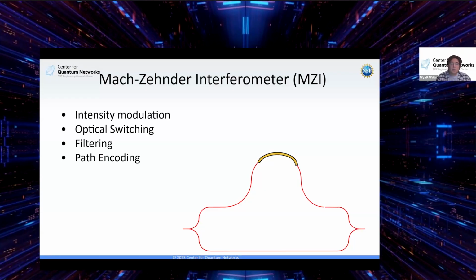Another thing you can do is use it to help filter out certain wavelengths. Because remember dispersion, different wavelengths are going to move at different rates and have different phase information at the end of this MZI. And so this MZI has what's called a free spectral range, in that if we took a very wide spectrum, looking at all these different wavelengths that go into the MZI, only certain ones go through. We can use this for some selectivity, and especially when it comes to our very discrete pump signal idler photons, that becomes very important.